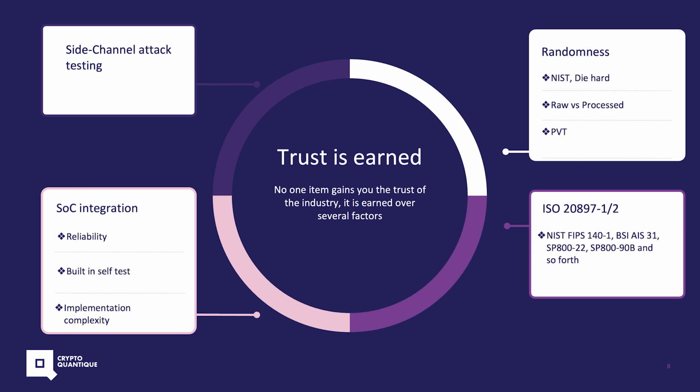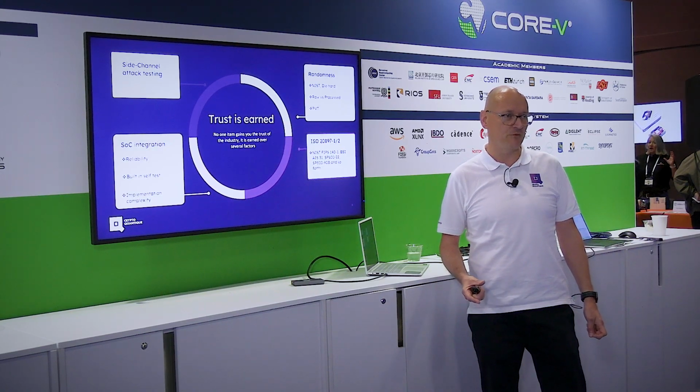That helps. And are you testing across process? Are you testing corners, wafers, time, temperature, high-low testing, things like that? Side channel attacks. Is your PUF vulnerable to side channels?